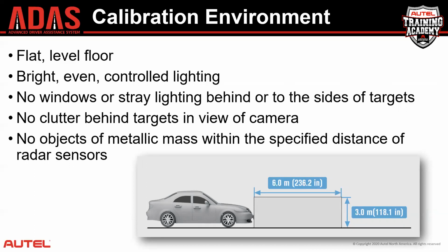It wasn't accurate. And then for radar calibrations, the OEM will tell you how much free and clear space is necessary to perform that calibration. An area in which there are no objects of metallic mass that would confuse a radar sensor and cause radar reflections back to the radar sensor, causing a failed calibration or, again, an inaccurate calibration.